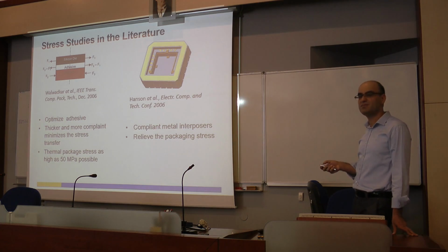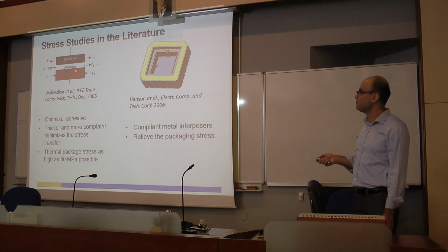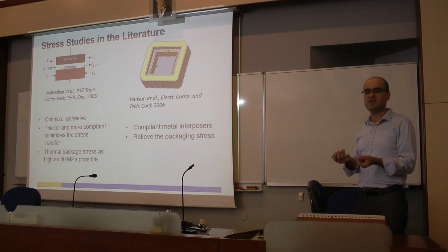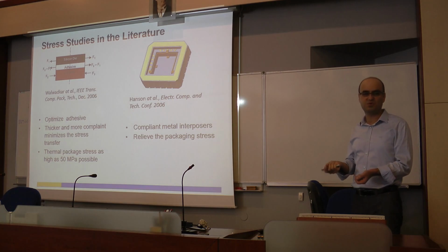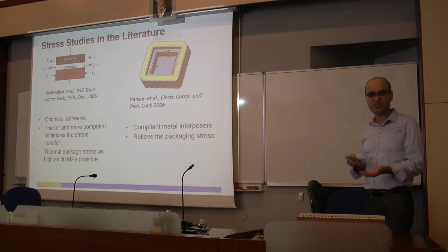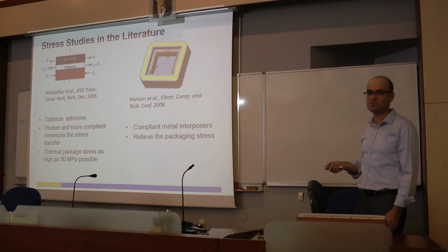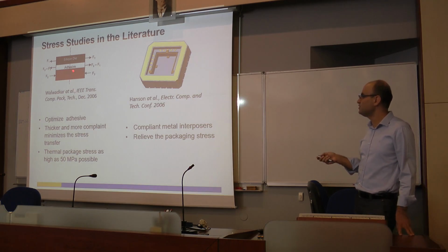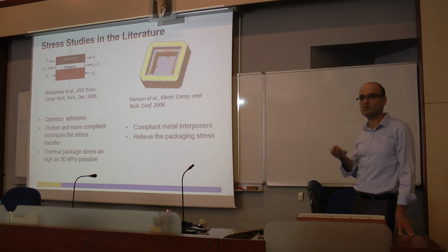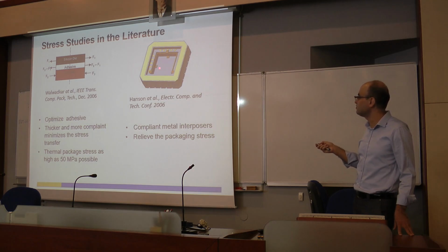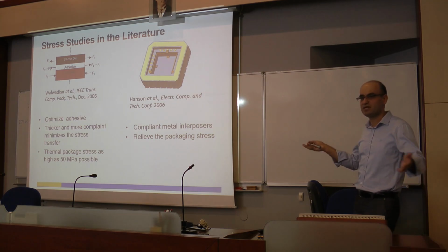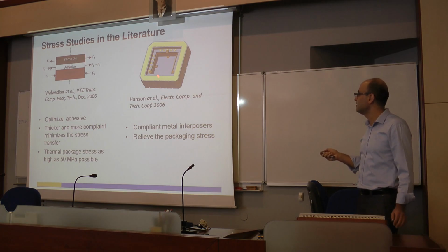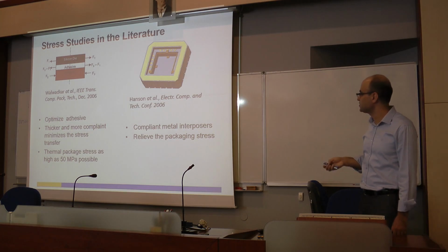And you want to make it stable, very soft. For example, if you don't want any stress to come to your device, you want to make your adhesive very soft. But if you make it very soft, then the problem is it becomes humidity sensitive, and it absorbs moisture and it causes different stress on your device, which cannot be understood very well. So people try to optimize the adhesives. You have to make it soft. Or they did something like this, where you mount your device on the bottom, so that it's very compliant. Whenever external stress comes in, this relieves the stress. But as you can imagine, this is not very easy to manufacture.